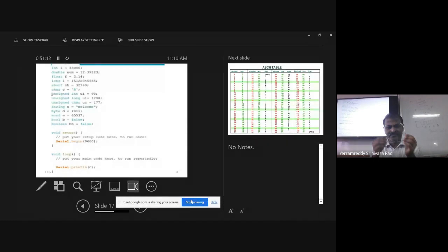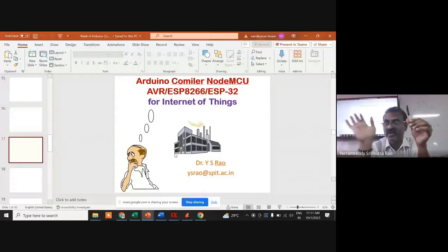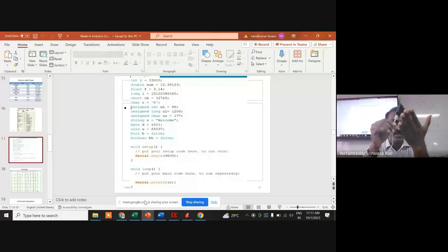Okay, so what is the procedure whenever you plug it in? I told you don't use the baseboard right now, and don't keep this on metal plates because these are conducting pins. Keep it on a non-conducting surface, either wood or a book, whatever, plastic. There you keep it.